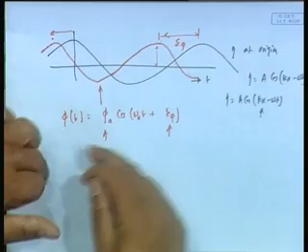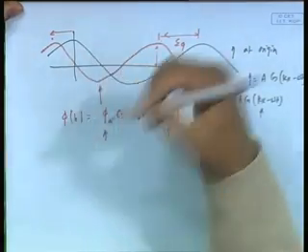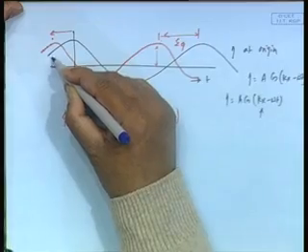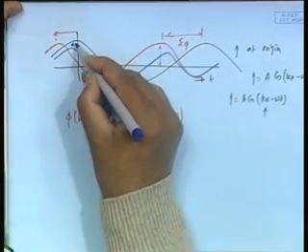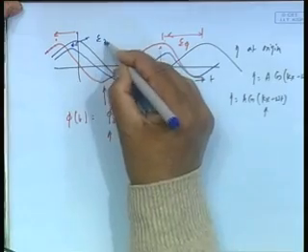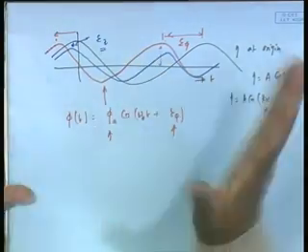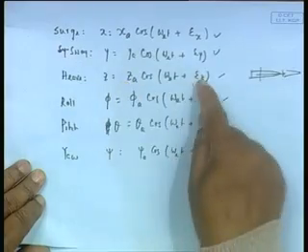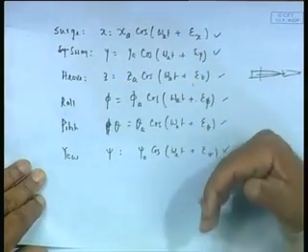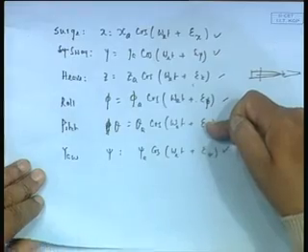Now, let us call this roll, and let me also take another signal, it can be pitch also, but let us say heave. So, heave will look something like that, where this will be the measure of E z, the heave signal phase. All the ship motions would have these components, their own amplitude and a phase, and between these two, if I want to find the relative phase of heave with pitch, it is E z minus E phi, etc.